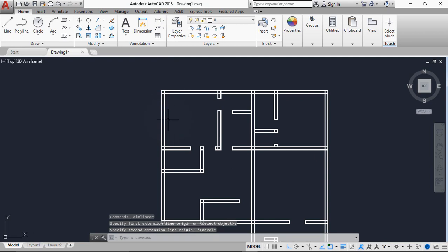We already know, no, we don't need to measure. To do that, we divide our room into two. We know that our kitchen is 4 meters at this length, and we want to place a window of 1200 by 1200. If you remove 1.2 from 4 meters, you'll be left with 2.8. So 2.8 divided by 2 will be left with 1.4.